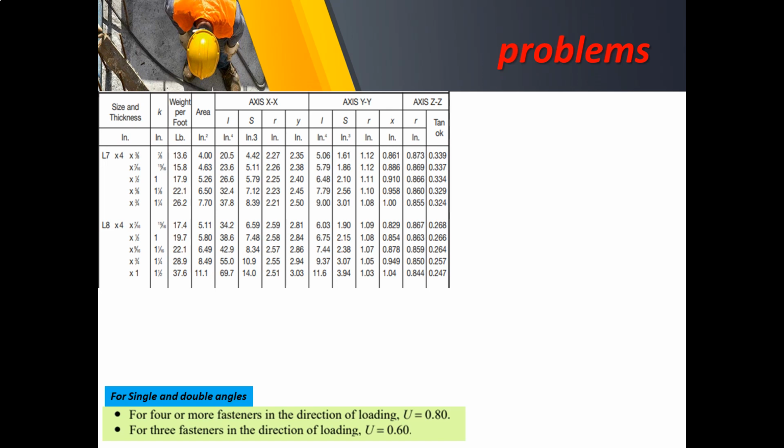So I would like to reiterate here to avoid several trials as presented. What we do from these requirements, we know that the reduction factor that must be considered here is U is equal to 0.8. Having that, when our trial area is eventually reduced by 20%, therefore, we anticipate to increase the trial area by 20%.